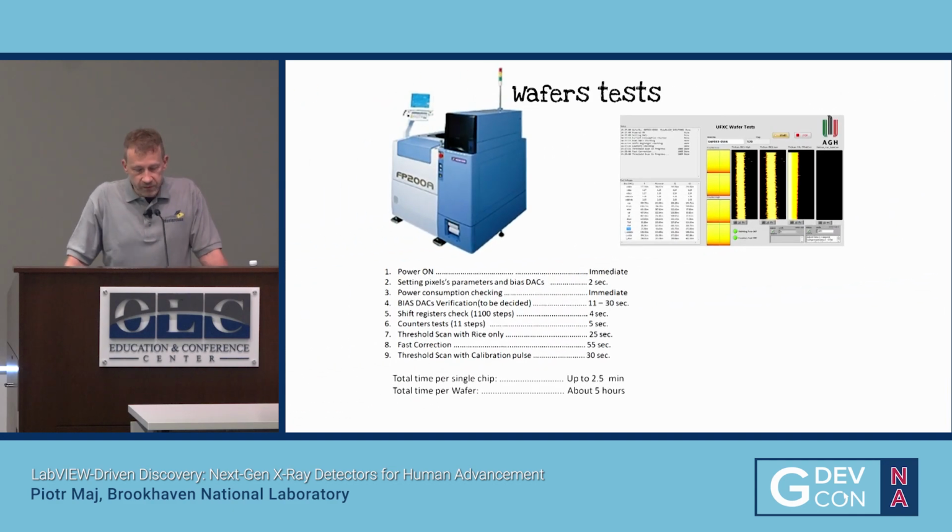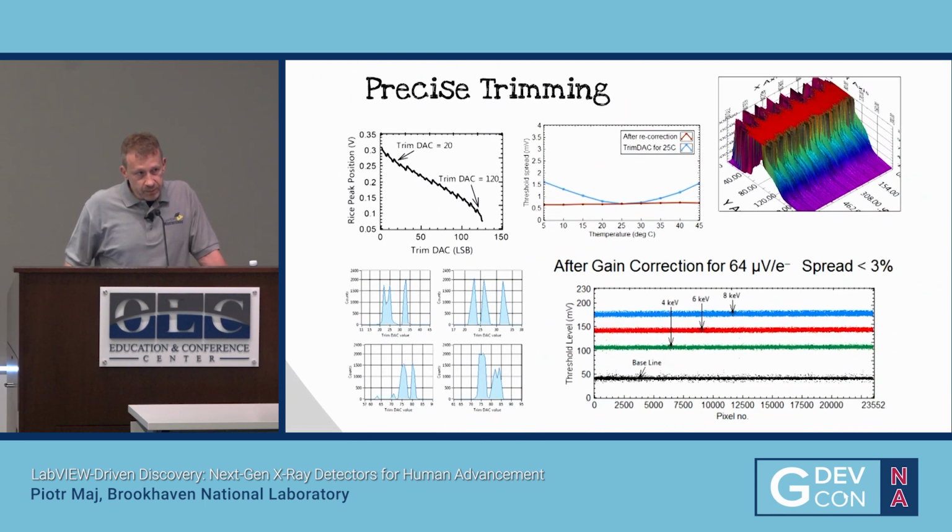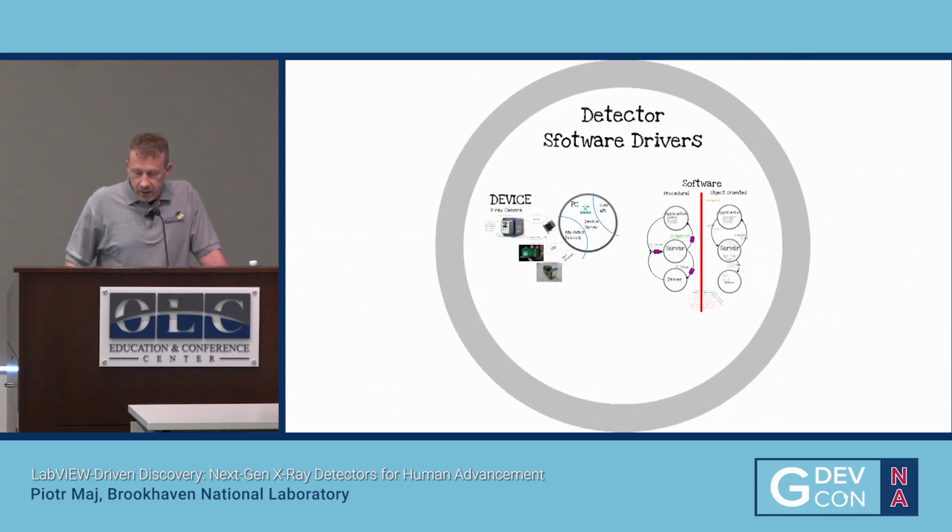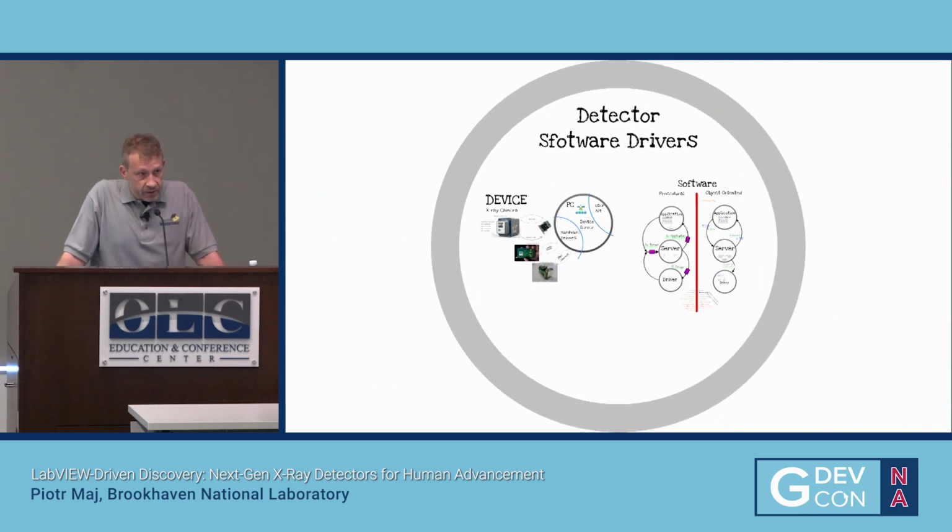In the process of development of this detector, we still use LabVIEW. We use it to verify wafers. We use it to trim the device before sending to clients. And if you get the device and connect it to the PC, the data you get to the PC is actually taken by the software written in LabVIEW. This is a data server. Just about this application was the subject of my presentation at CLA Summit in Paris 2012. And the application still works, is still under development.